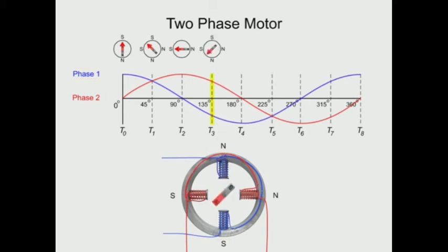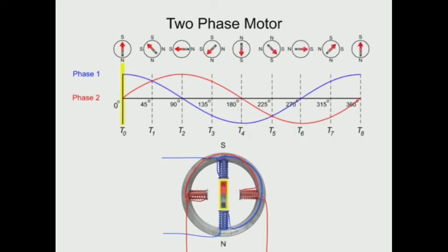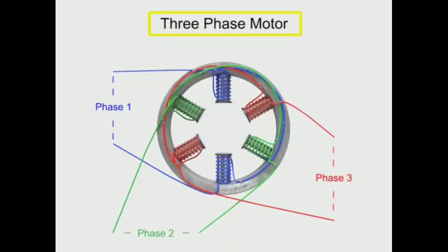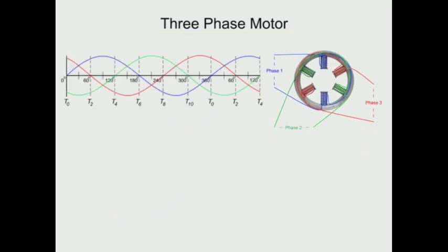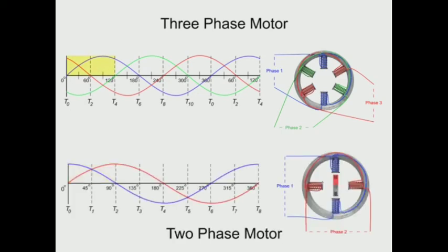the latest step. Thus, continuous rotation is achieved by the input of a train of pulses, each of which causes an advance of one step. It is not really continuous rotation, but discrete, stepwise rotation. The rotational rate is determined by the number of steps per revolution and the rate at which the pulses are applied. A driver circuit is necessary to convert the pulse train into proper driving signals for the motor.